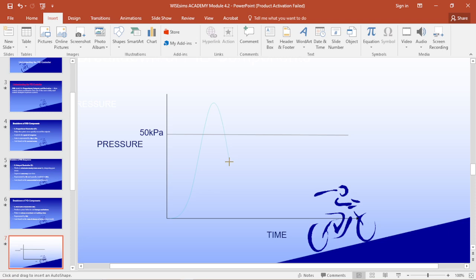Once it begins to overshoot and then comes down below, it tries to go back to get to the set point. This thing that is happening here is called oscillation. So now your integral controller kicks in, and it reduces the overshoot and the error. Instead of coming back to this point, the integral controller reduces the oscillation. Now it's going to be coming down.